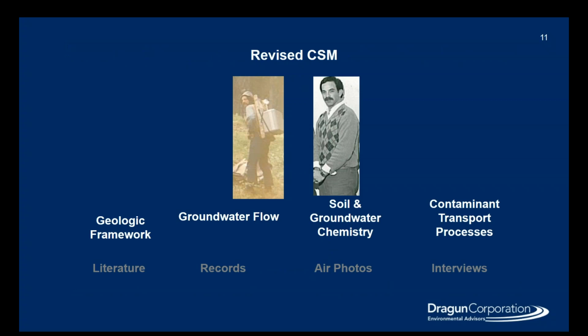In a revised CSM, one that's even better, you start adding information by getting information in the field: geologic framework, measuring groundwater, water levels and velocities and so on, taking samples of soil and groundwater chemistry, and looking at the contaminant transport process. In the analogy of my career, new professor, lots of book learning, some lab work, but not a lot of experience doing practical things.